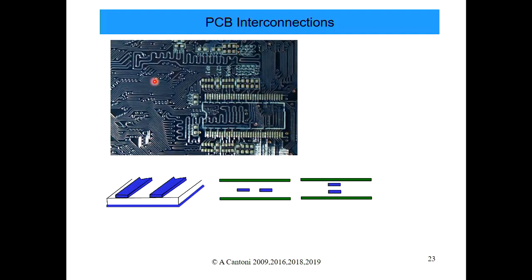Maybe if you put them in an LC or RLC network, then in some sense you can say it's got delay, but the actual component itself doesn't have delay, okay? It's just V equals I R, the relationship between the voltage and current at a resistor, right? So it's instantaneous, okay? Change the voltage, you change the current. Same with a capacitor, I equals C dV/dt, right?